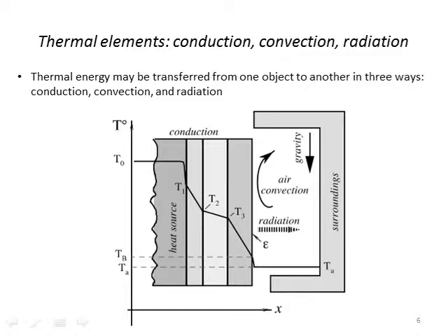And you can almost think of this as the conduction across here is like a resistance, and you're going to drop a voltage across a resistor. Here you drop a temperature across a particular slab. So you have a certain thermal resistance that's going to basically drop a certain temperature across it. So we drop from T1 to T2, T2 to T3, then T3 to the surface, right at the boundary of the surface.